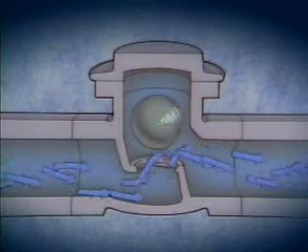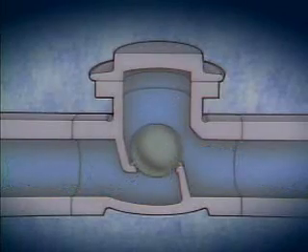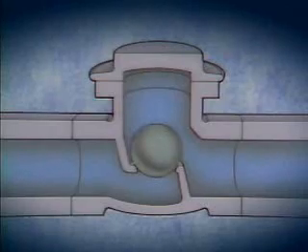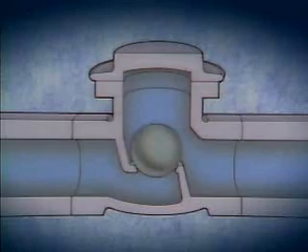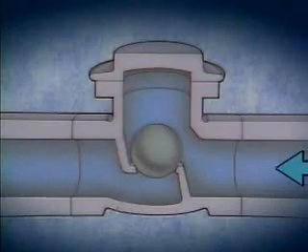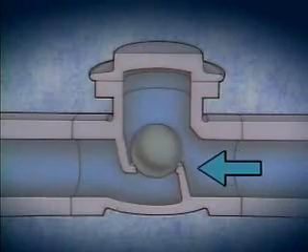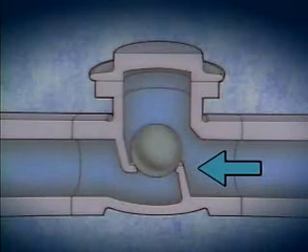When flow through the valve stops, the ball is pulled onto the seat. A different surface area of the ball falls onto the seat each time flow stops. This produces a self-cleaning effect that also helps to ensure that the valve continues to close properly. If flow reverses, the backflow holds the ball firmly on the seat, keeping the valve closed.